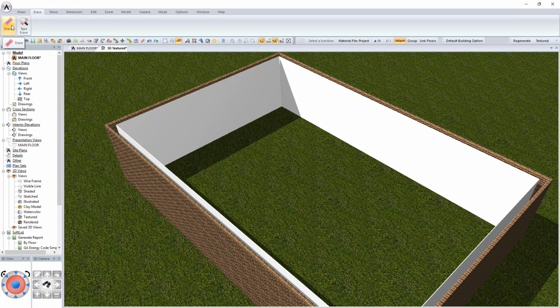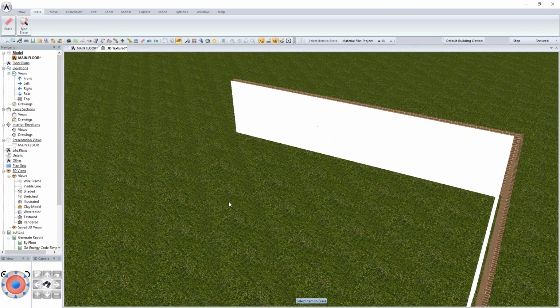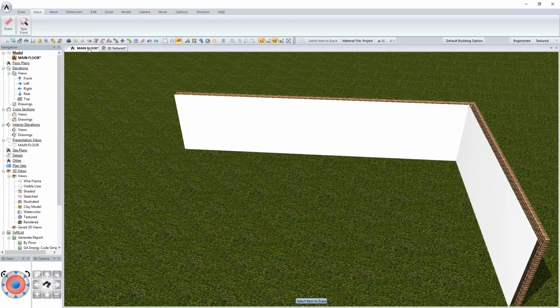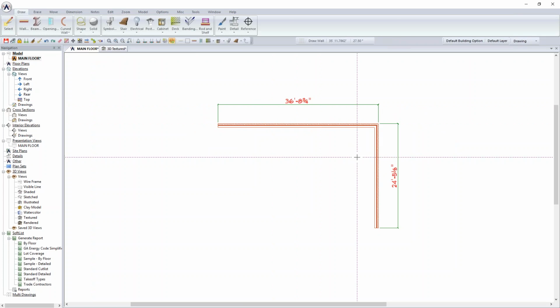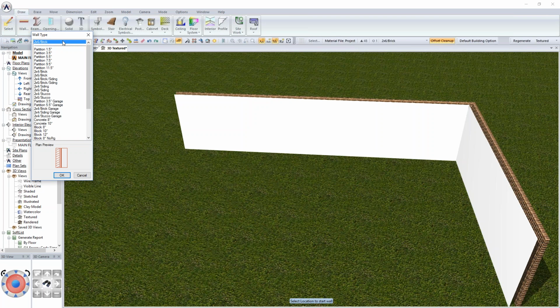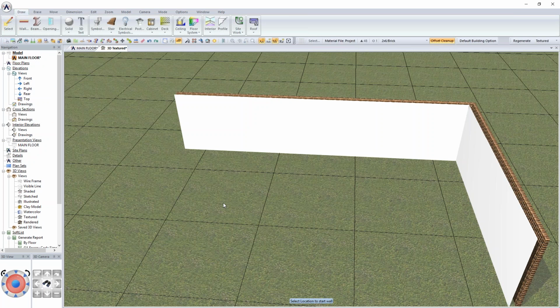So for example, to demonstrate this, I could come in through Erase and Item Erase. And I'm going to remove the last 2 walls that I just drew, okay, so that we're back to just these 2 walls. And you can see, there they are. All right, if I come back into the 3D texture mode and I pick Draw, and there's the Select tool again, or I could simply go to Wall and pick the wall type menu. When I do that, you will see that I will get a grid on my 3-dimensional grass there. And those are basically 10 by 10 blocks.